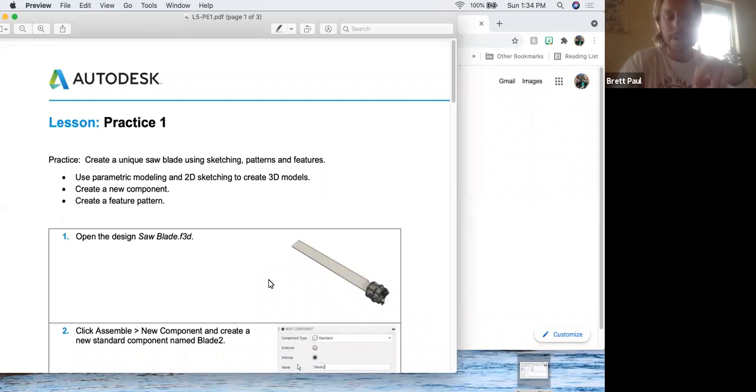So far, we've only extruded using 2 different tools. We've covered a sweep extrusion, where you create the path that you want the profile to extrude along. And we've also used the basic extrude tool, where you take a certain profile and give it some depth.